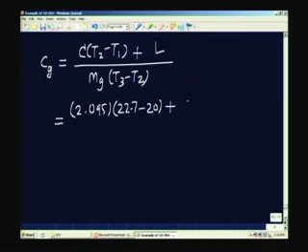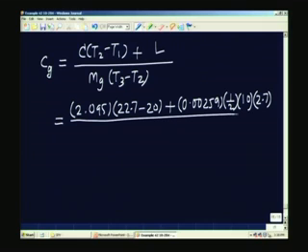K itself is 0.00259, and the integral is nothing but half the base into altitude, 2.7, divided by the mass of the glass beads multiplied by the temperature change, that will be 150 grams or 0.15 kilograms multiplied by 80 minus 22.7.